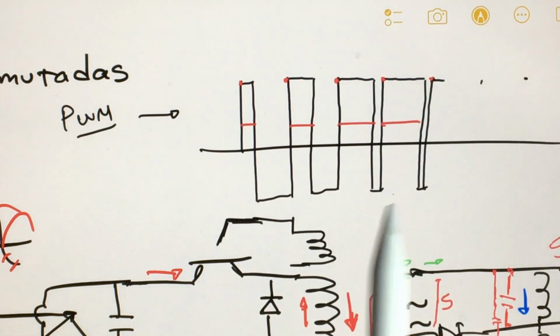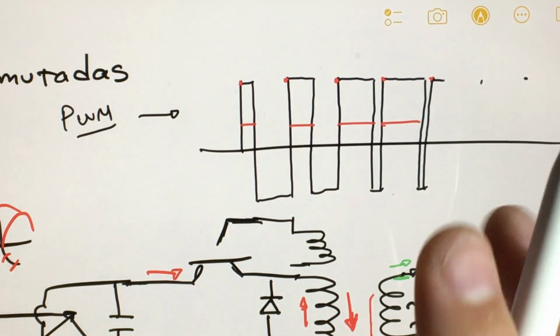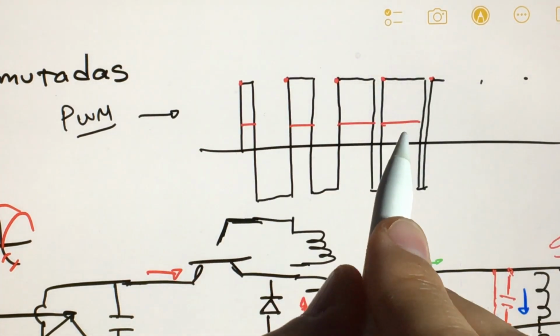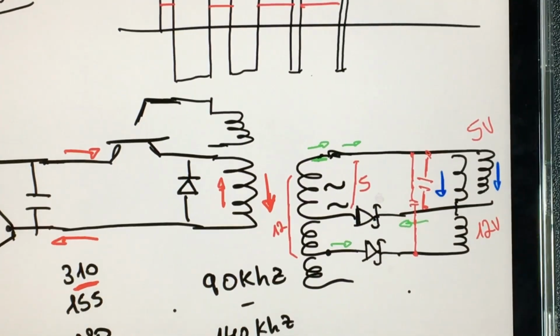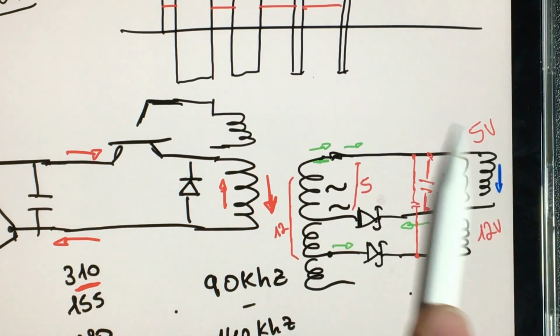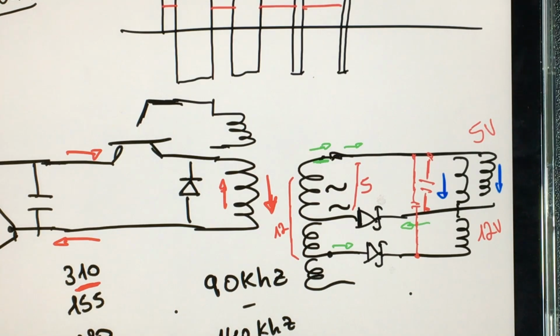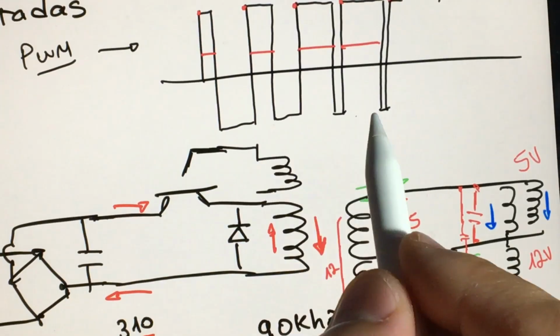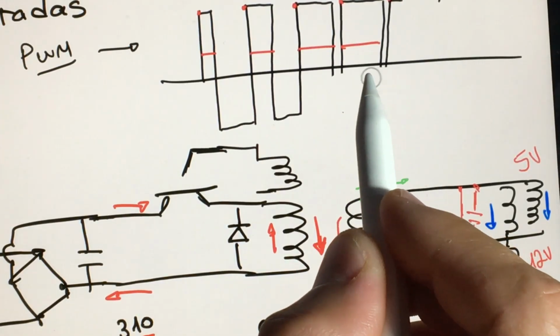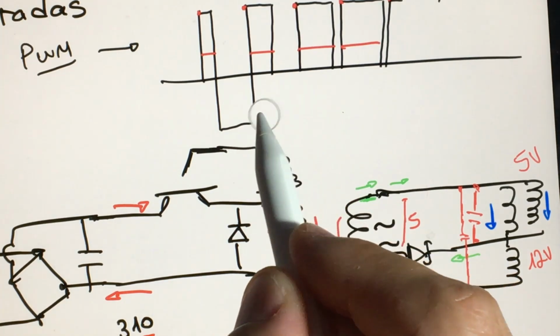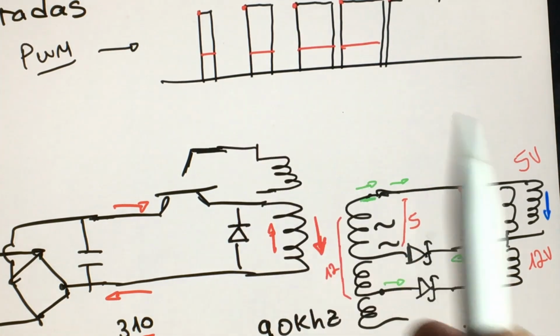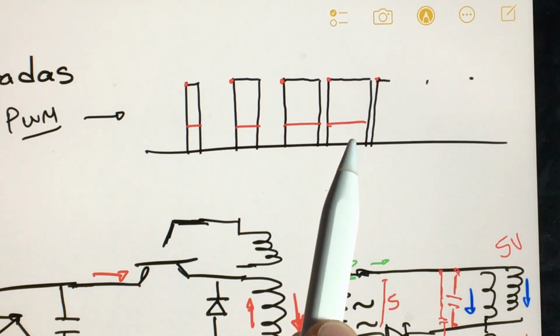This can be done by a switched mode power supply, and what regulates is the width of the wave that goes up. The switched mode power supply knows that on the other side of a half-wave rectification the wave below is lost, so if more power is needed, it makes the top wave wider. And if less power is needed, it makes the top wave narrower.